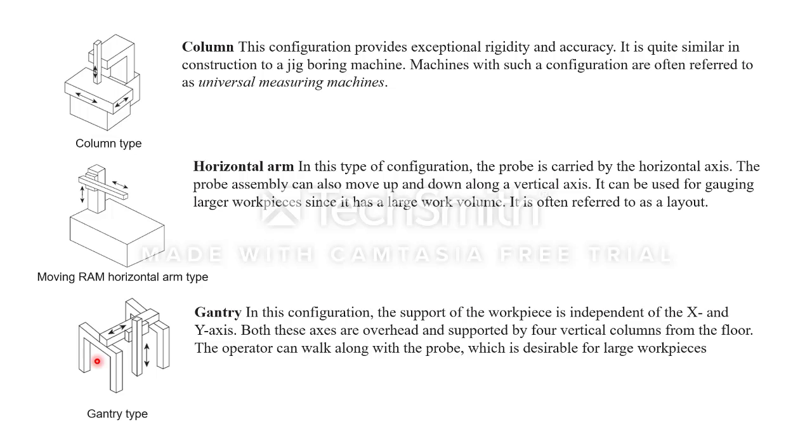And for every coordinate axis, the XYZ system, there will be a limiter available in the CMM machines. We'll call it an axis limiter. And if the measurement I need is a precise measurement, then you can install a laser interferometer.